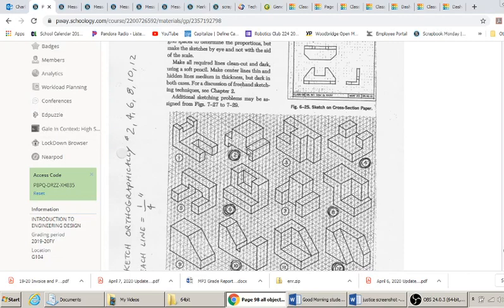These side shoulders are 2.5 squares high, so it would be 5/8 of an inch, 0.625, and it looks like these shoulders are 1/2 inch in each direction here, and then you have the little space down here, which is 1/4 of an inch up and 1.5 inches wide there.